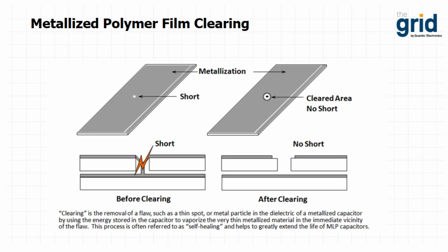Common to nearly all metallized film capacitors is the ability to self-heal, as it is called, in the event of a high voltage transient or even a mechanical activity that results in dielectric breakdown of the film capacitor or polymer capacitor. The polymer dielectric material will actually fuse around this fault and isolate. The capacitor can then continue to operate after the clearing event with minimal damage to the capacitor itself.